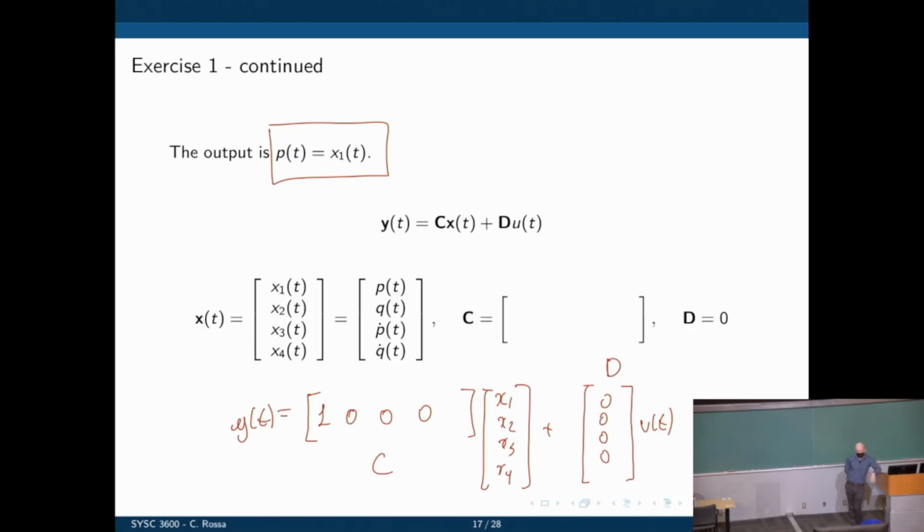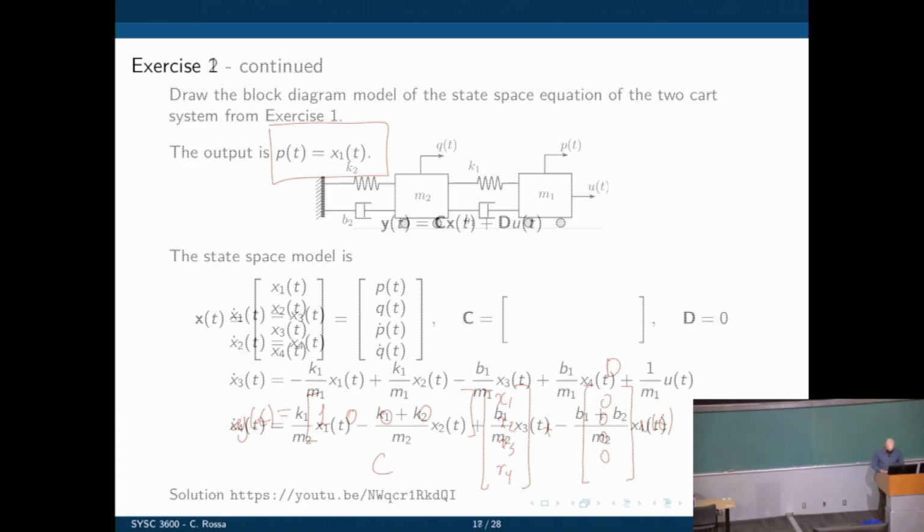Now, one thing that I mentioned in the beginning is that the advantage of this is that we can solve for these equations using a matrix format. Well, that's that, and there's nothing much to say about it. But the other advantage of this representation is that we can put that in a simulation diagram. And this simulation diagram now will explicitly show us where these states are. And then you can probe them with the appropriate scopes in Simulink, for example, and get access to that variable directly.